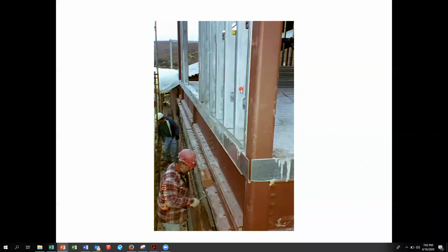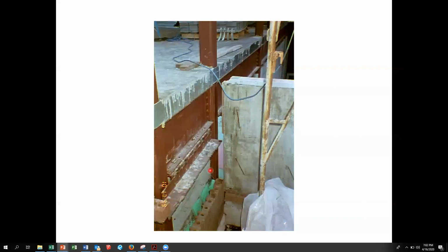Up here, they're offices. So now it becomes a steel stud with an exterior grade sheetrock screwed to this face of the steel studs. And then those same kind of brick ties tie in with the brick as the brick starts coming up the wall. And that's what you're actually going to work on next semester.